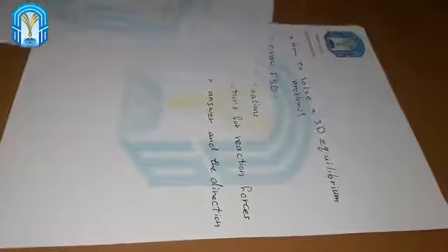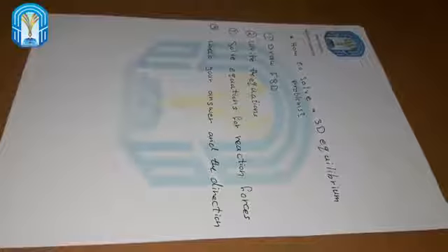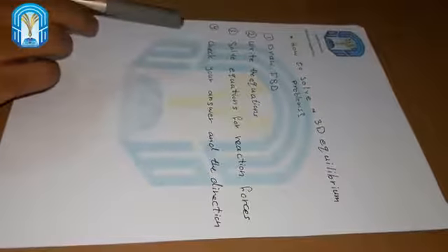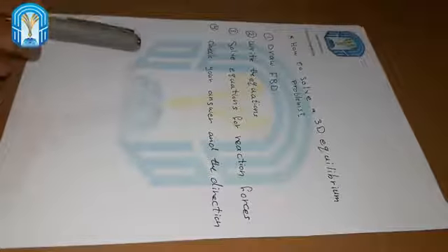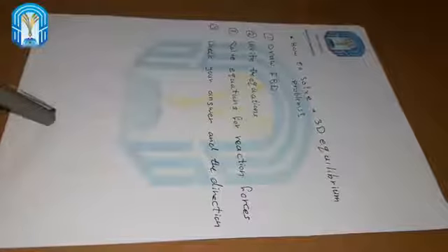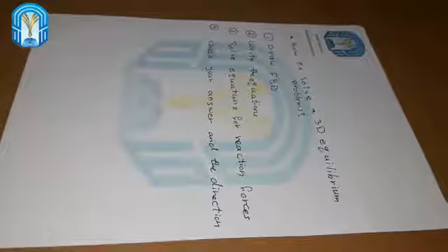Now, how to solve 3D equilibrium problems? First, draw the free body diagram. Second, write the equations. Third, solve the equations for the reaction forces. The last thing, check your answer and the direction. Now, we will solve some problems.